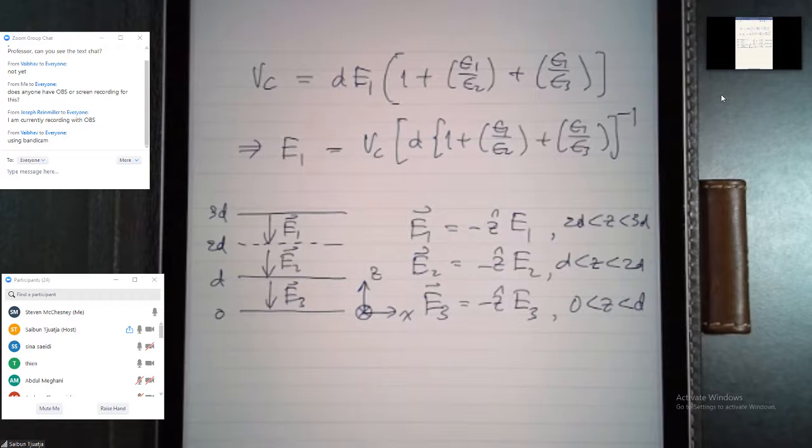So what have I used to solve for the field inside this layered capacitor? Very simple. I recognize the relationship between different regions, apply the boundary conditions, and I also know that field multiplied with distance gives me a potential. The total potential between the two terminals up here has to be equal to V_C. Therefore, I can solve for E because they are all related. Once I figure out one, I can solve for the rest, and then I specify the geometry so that I can put the vector notation appropriately. Any questions at all? That's the first part.